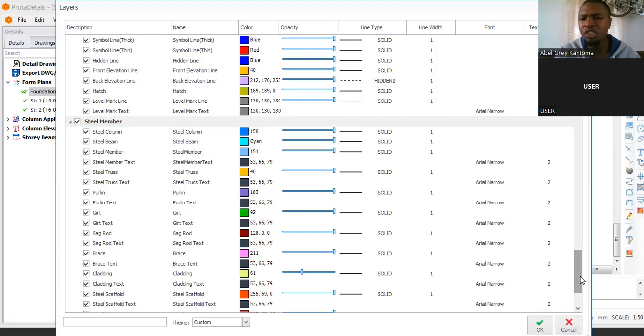Okay, when you use such kind of colors, it will most likely come out very, very clear. And then you can change the thickness of those lines, most especially when you check your beams. You're going to see those beam reinforcement, they don't really come out very thick, they come out very tiny. And then the type of color that it actually gives to you are colors that when you print out your detailed drawing, it does not really come out clear.